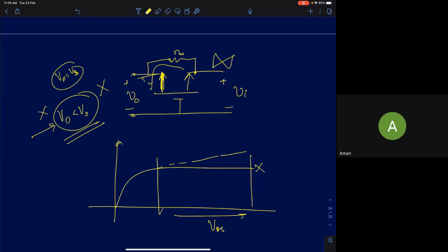But I'm telling you that this should not be the case, because you have clearly configured your amplifier as an amplifier. So you have connected load resistance to the drain terminal, and you're supposed to deliver power to the load resistance. For that to happen, you need to have the drain potential to be higher than the source. Okay, so let me come back.